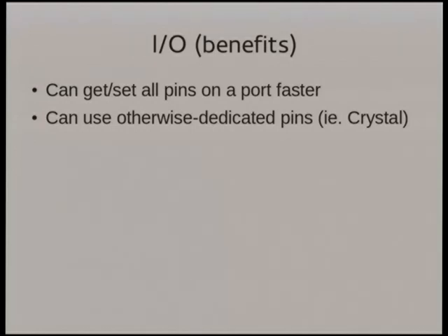One of the other neat tricks that you can do is, because we're not using a crystal on this chip anymore, you can reuse those pins for input and output. And you probably should never do this, but it turns out you can also use the reset pin for output. It sounds really crazy, but on the 8-pin devices that's actually kind of handy because you've only got a really limited number. Once you've got a power and a ground and a couple of input and output pins, you run out of pins really quickly.